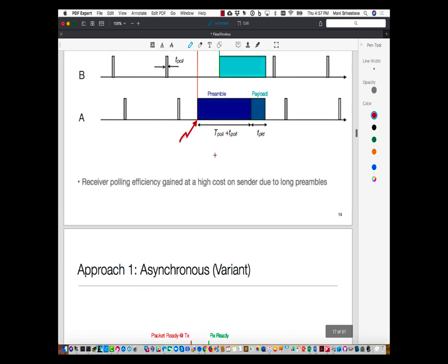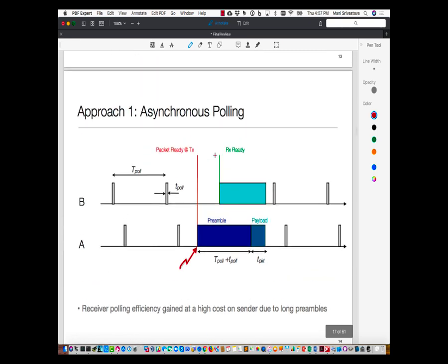Whereas in this scheme, there's no transmission happening. All you're doing is waking up, listening, and going back to sleep. So if there was no event happening, nothing will be sent out over the air, since I'm not transmitting anything. That's one advantage, although you could argue that if it's a short-range network, not transmitting is not that big a win because I'm losing energy waking up anyway.